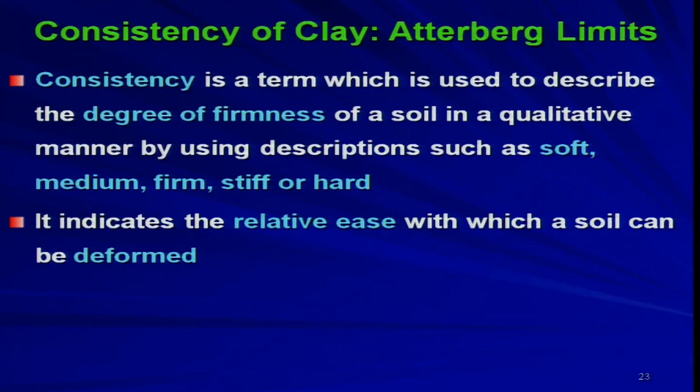So, it indicates the relative ease with which a soil can be deformed. It is very simple. The clay soil will have the property of a deformable material, so the consistency will indicate how easily I can deform the sample.